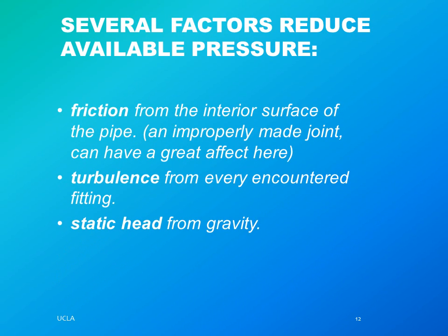When we talk about velocities, I size for 5 feet per second for cold water, 4 feet per second for hot water, and 3 feet per second or less for hot water recirculating, because that's moving all the time. Hot water is more abrasive, has more dissolved air, presumably, and if it's recirculating, it's running all the time. So we want to take care not to erode the piping.